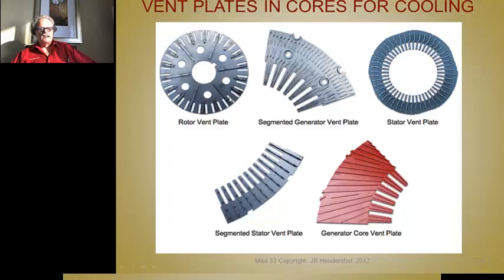But what these consist of is a fairly thin piece of steel with stand-ups on it. These are all various shapes and contortions of these. See, even this spreads the stator teeth apart. These little stand-up blades are usually stamped, formed, and welded in jigs. Some of them are handmade, some are automated, semi-automated. You don't find these in small machines, but I think more and more you're going to see that in the future.